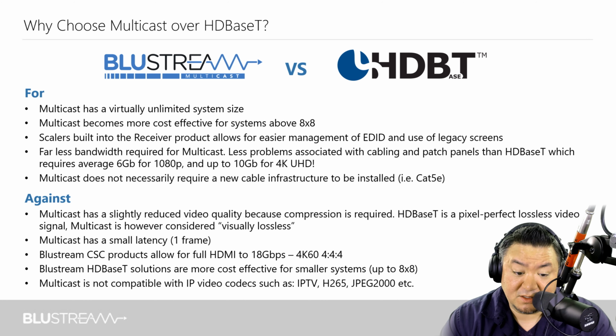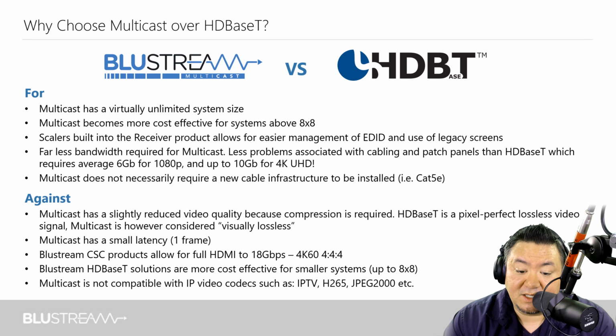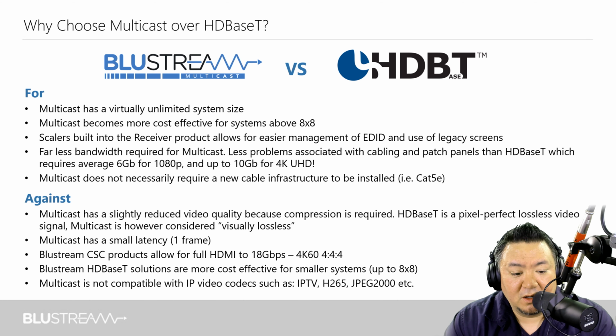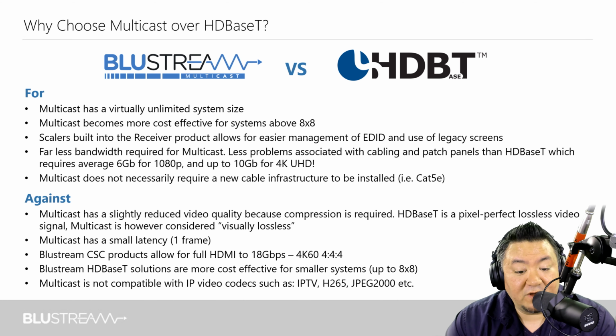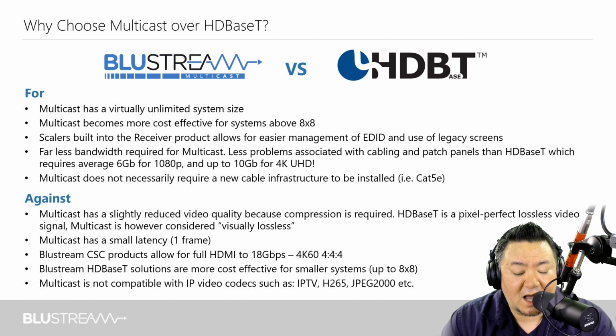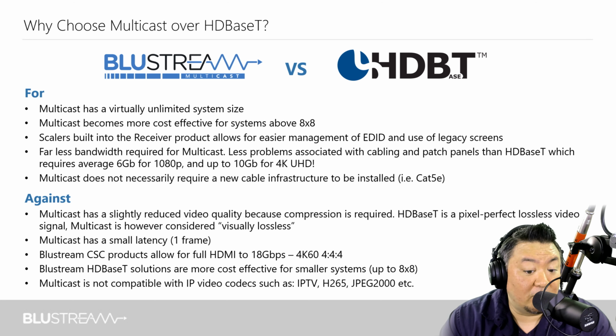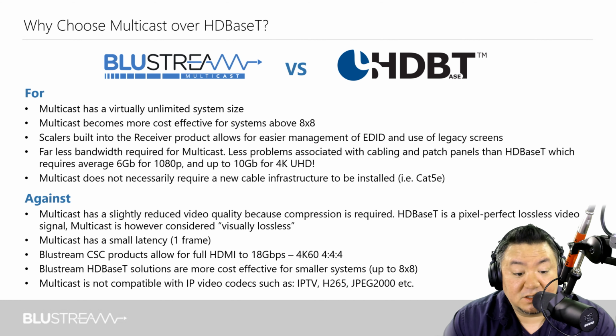However, stating this, we do foresee AV over IP taking more market share away from more traditional styles of AV distribution. For example, with Multicast, we have the ability to scale installations with ease, adding an input or an output as needed. And if an individual endpoint fails, these can be replaced very easily. Using standard IP technology to broadcast video signals also gives us an easy avenue to use existing equipment being deployed for IP networks today, such as patch panels and switches.